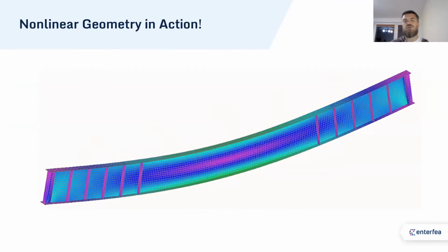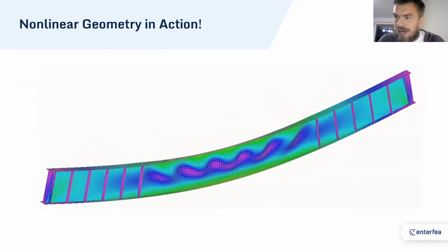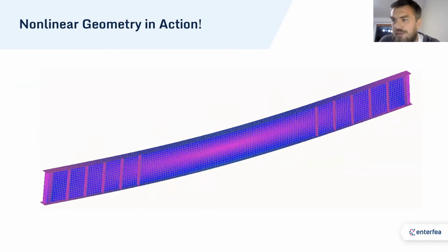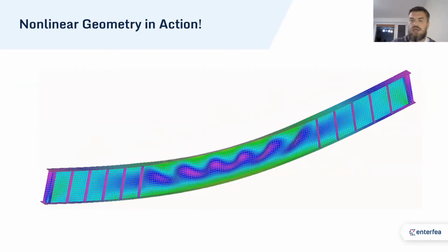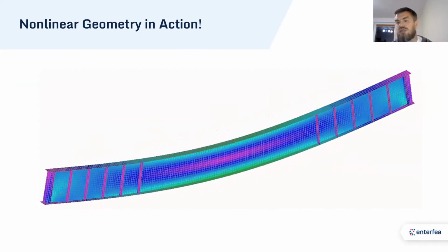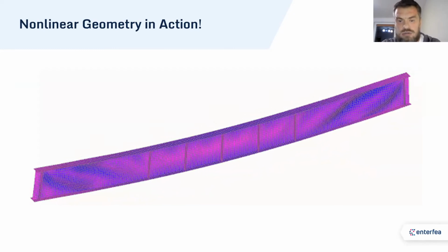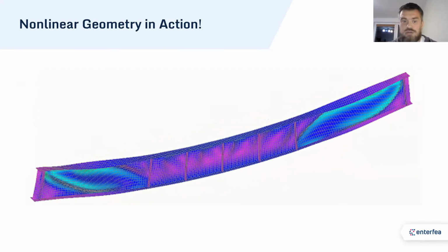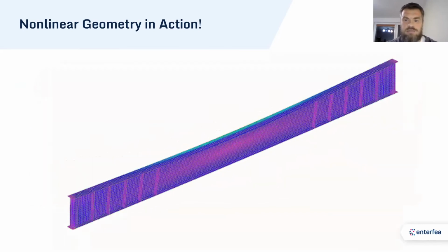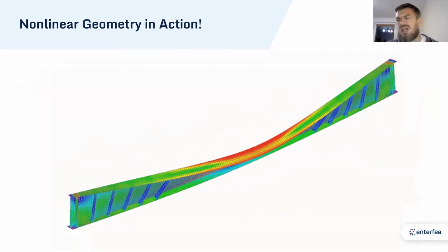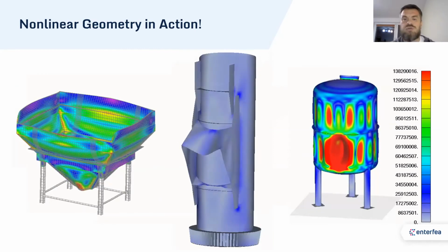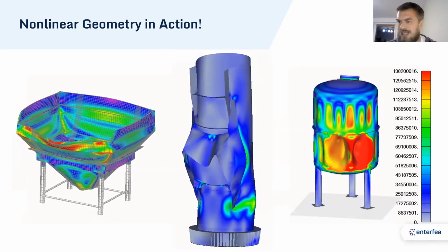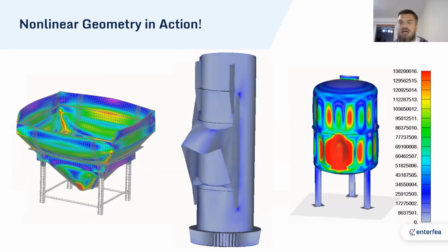So this is why, to analyze it better, instead of using linear buckling, it's better to use nonlinear geometry, as this is a way more reasonable approach. And as you can see, nonlinear geometry allows you to calculate local stability. You can calculate shear stability, the one that's very difficult to catch if you're not searching for it. Lateral torsional buckling, yes, it's doable, although there are easier ways to design beams in bending if you're using structural design. And then, of course, you can do all kinds of weird analysis that would calculate bizarre failure modes